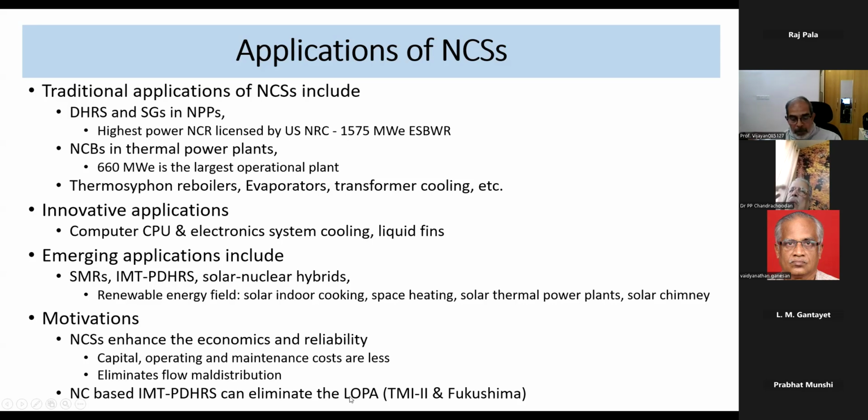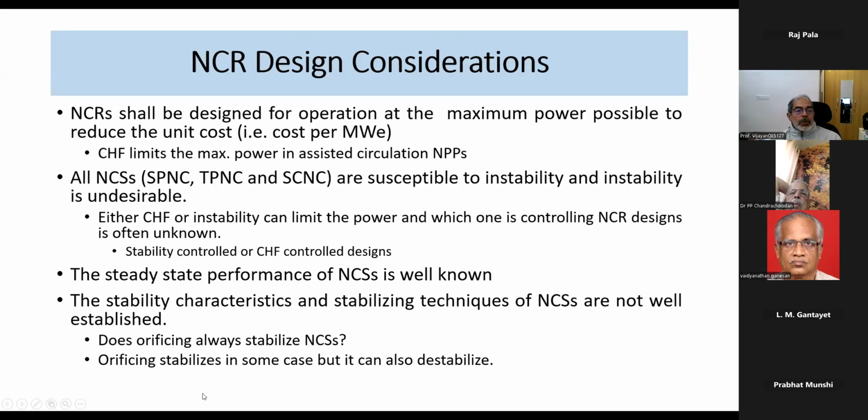And of course, the loss of plant accidents like those at TMI-2 and Fukushima arose not from the physics point of view, but from the thermal hydraulics point of view. That is because they didn't have what is called infinite mission time passive decay heat removal.